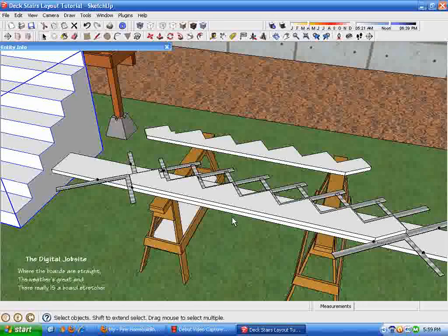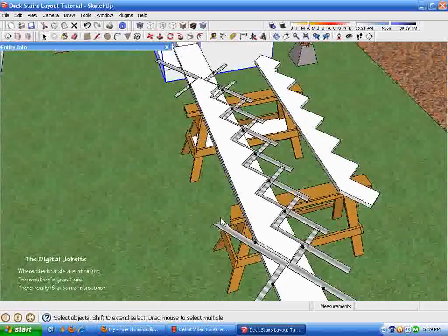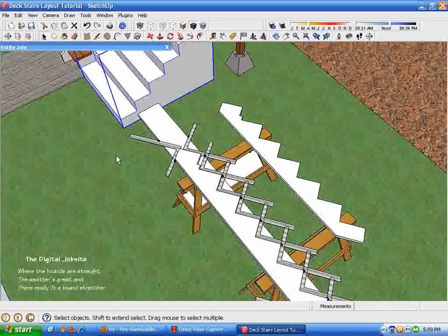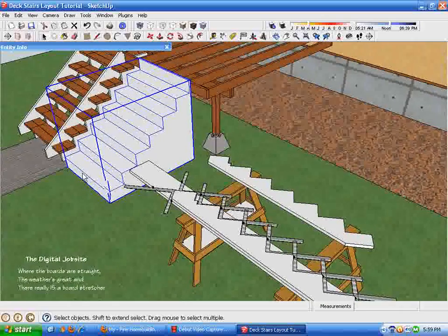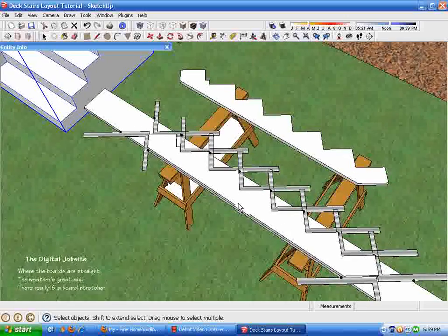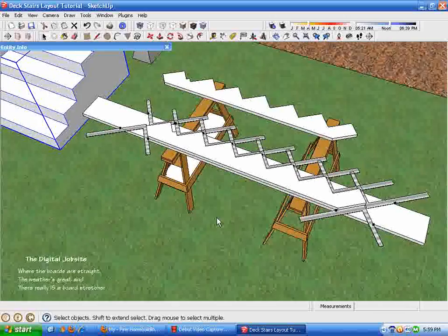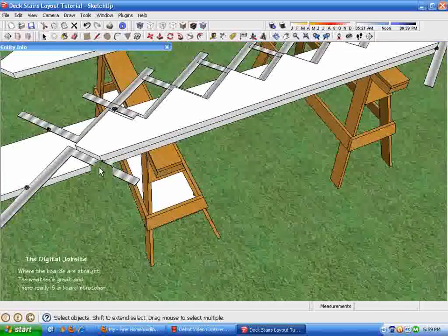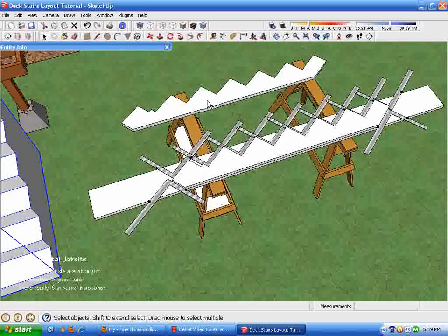And the setup over here I put together as a representation of using a framing square to apply the measurements we got from the calculator and the connections and relationships we got from this tutorial, how those are applied to a 2x12 to do the actual pencil layout, so you can cut this layout. If there's interest in that, I can expand on the topic a little bit, showing how a person would go through this process by orienting the framing square, stepping off the dimensions, etc., to end up with completely accurate stair stringers for a set of deck stairs.